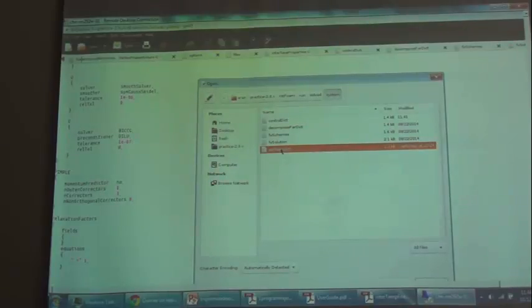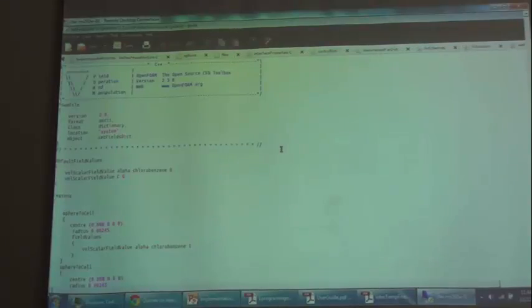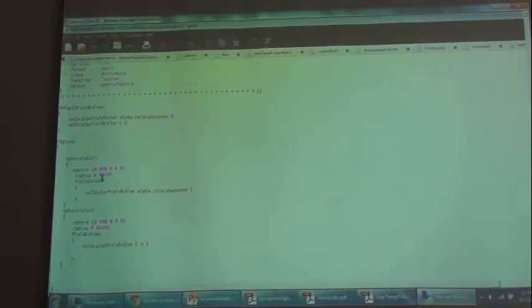That's it. And I have another dictionary called setFieldsDict. This will be used for initializing the case that I will be running, which is basically a rectangular domain into which I will be patching a sphere and releasing it. That sphere would be defined by this. The center of this sphere is defined by these coordinates, and it will have a radius of around, it's basically a 4.5 mm droplet. This is how you achieve initialization.